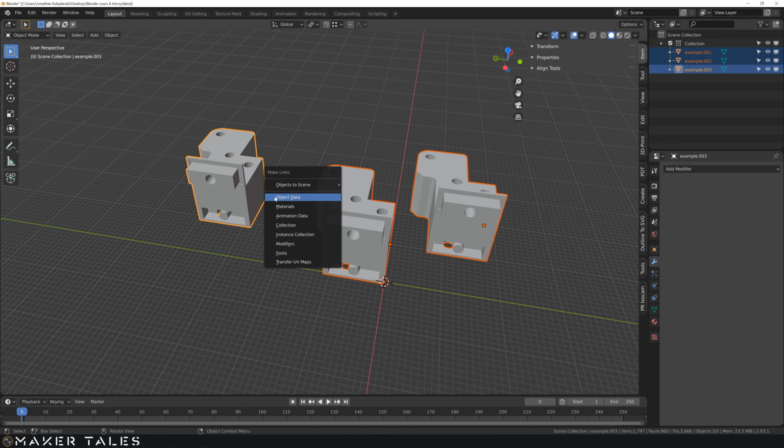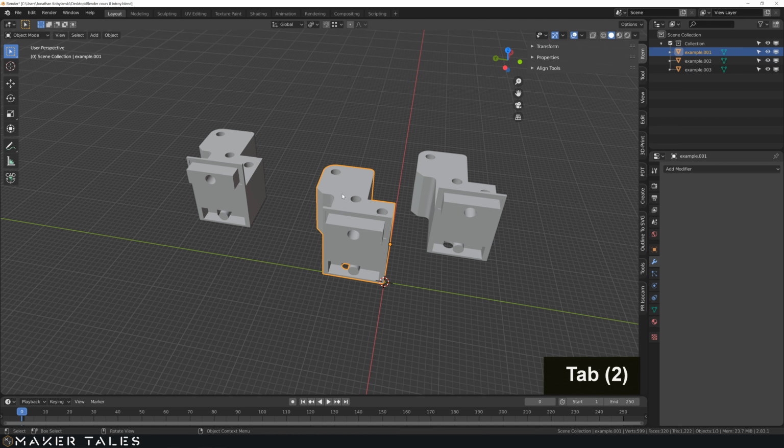And what we're going to do is object data, and this now has linked all of these up together, and you'll see that if we click on any of these, it is now linked. So of course we can select one, we can go and use our new shortcut of Alt U, say yes, and that there is this one now unlinked, and the others will be linked.